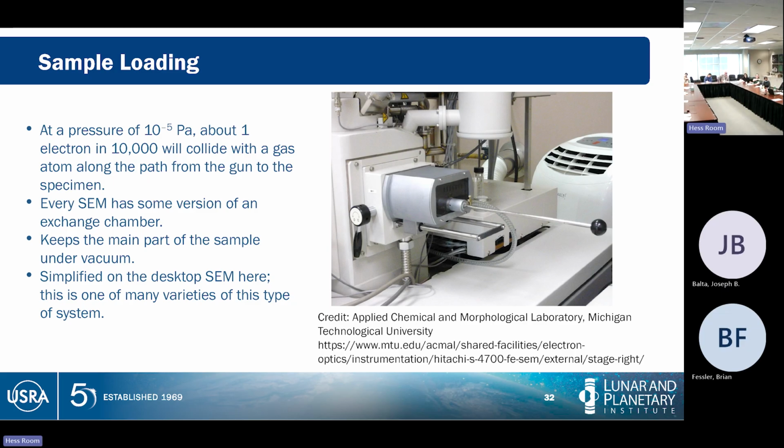For example, with this specific type of SEM, if you don't load your sample in properly, your sample can fall off into the machine, and you wind up having to literally open up the SEM and take it out of vacuum to get the sample out that you dropped in. This is less than ideal. I have not made that error, thankfully, but I know of people who have. So if you're in a lab, pay attention to what they say in terms of sample exchange. This is one of the places where you can actually mess things up.